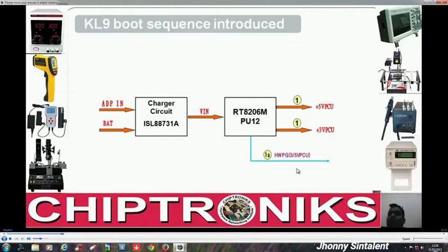And then the IO controller will issue another power good, and it will indicate to PCH that yes, all the power regulators are working. And if the IO controller doesn't generate a power good, then the PCH will not work. So this is all done to maintain safety, right? To maintain safety in a notebook. A notebook motherboard is very complex, but it's very costly also. So we have to devise a foolproof system.